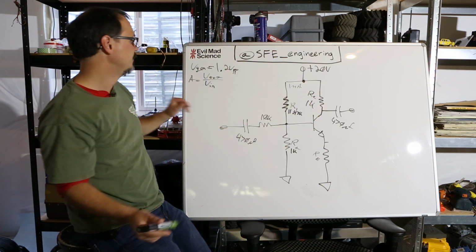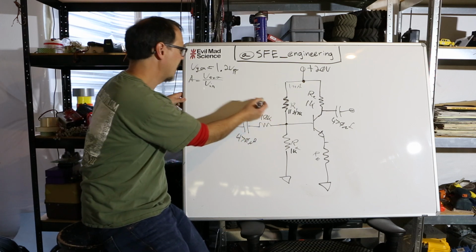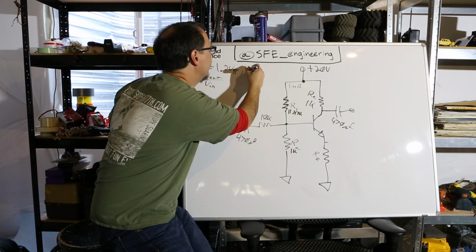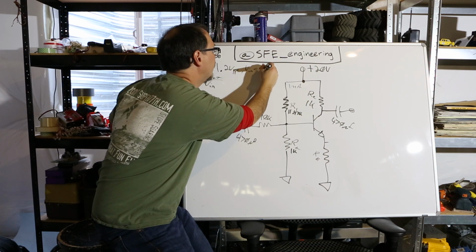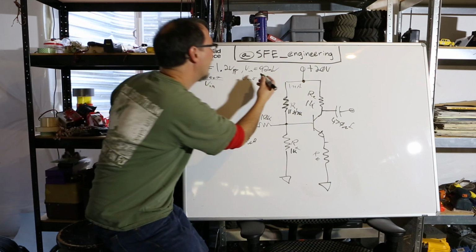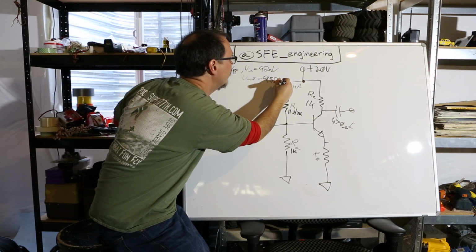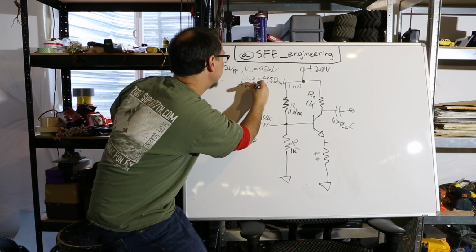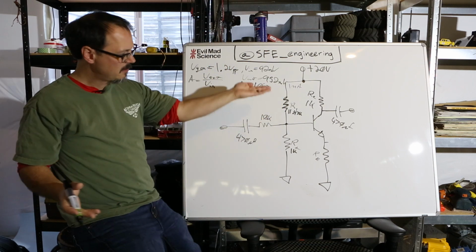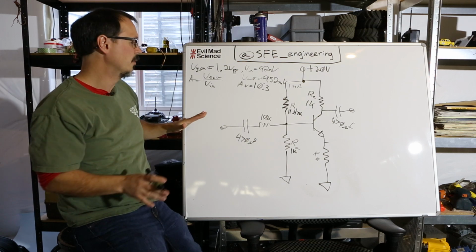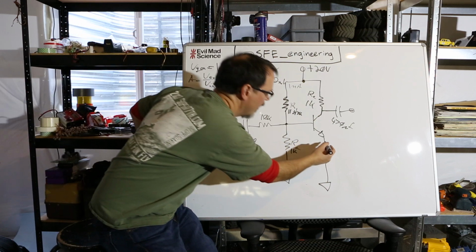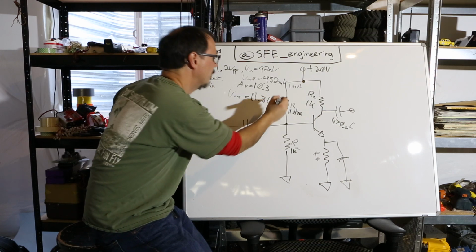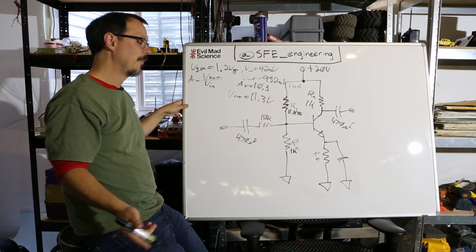When I set this circuit up and measured V in at the base, V in equals 92 millivolts. For V out, I got 952 millivolts. So that gives me a gain of about 10.3. AV equals 10.3. That's pretty close to what we expect, right? So we're cool there. Now you put the cap in. V out goes to 11.3 volts. That's quite a bit. That's a big jump.